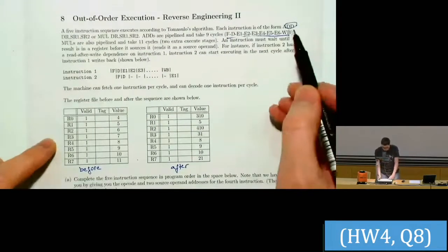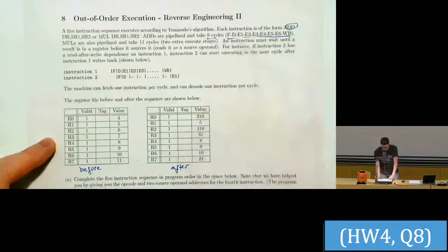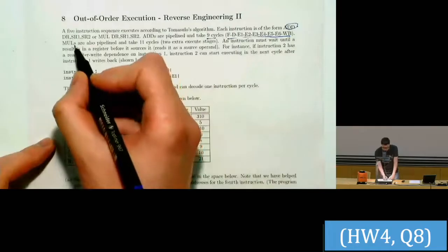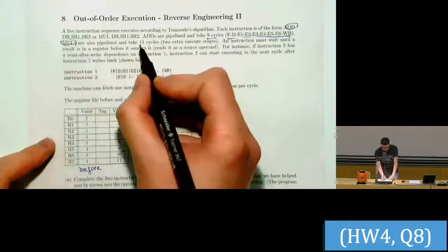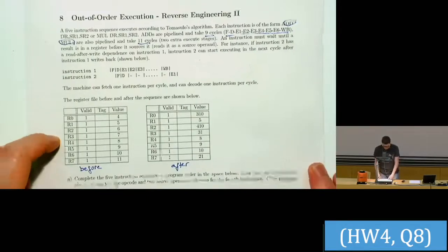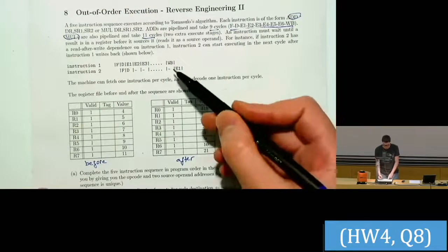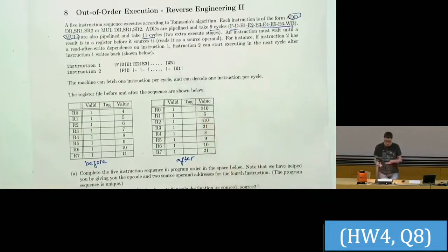Okay, yeah, as I said, the add instruction has those stages here. I think in total it's 9 cycles. Yes, it says it here. And then for multiply instructions, we have 11 cycles in total. So 2 more cycles in the execution stage. And the question is also describing it well, like what is the policy for reading back the data.